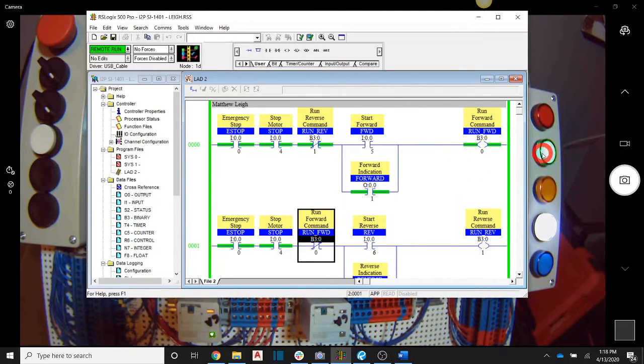So here you can see we've energized the relay right down here, and CR2 is off, so that's why our white light is on. And once our white light is on, we can use that for a holding circuit, and we cannot press the reverse button. You see, because this white light is on, because our run command is on, we have taken away this test for zero instruction. So if I try to hit reverse, you can see that the reverse push button is getting logical continuity, but they all have to be lined up in series for us to actually hit the reverse output.